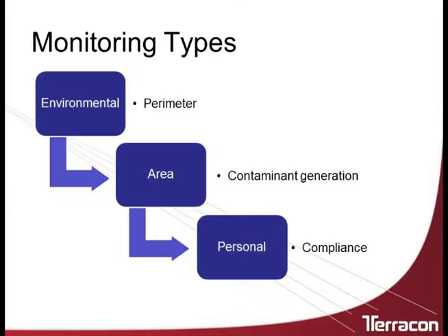Second, monitoring is area monitoring. And typically this is conducted to try to find out what the contaminant is and where it's being generated. This also comes in handy, like I said before, with respect to determining whether or not your local exhaust system is doing its trick. And finally, the one for compliance purposes is personal monitoring. And this is where you're actually equipping the individual with a pump and a certain sort of media in order to collect that sample, sending that in and having it analyzed.